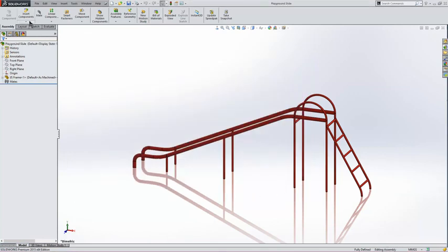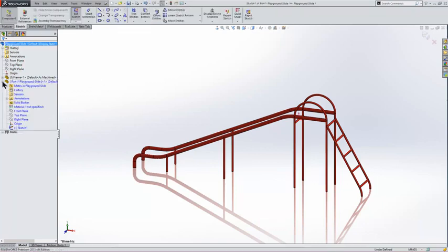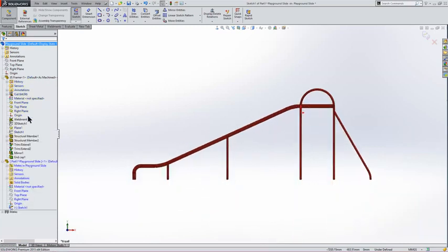Okay, insert new part, and we're going to select the front plane of this part to be the same front plane as the assembly. That opens a sketch on the front plane already for us. What I'm going to actually do is create a path for our sweep. And I'm going to follow the same path as the stringer of this member right here. So I want to make that a little bit visible. It's the 2D sketch, so I'll just make it visible. Select the sketch of the actual frame and convert the entities.